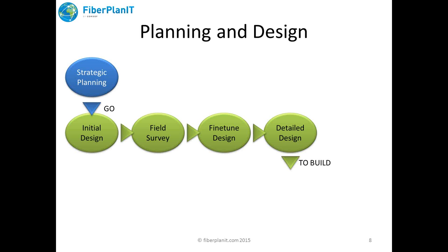Then in the next step, we foresee a field survey to take that design into the field and check if all the proposed locations of cabinets or manholes or places where your cables would cross the street, if that's from a practical perspective possible. So the field survey will come back with some feedback, and then it's important to be able to fine-tune the design